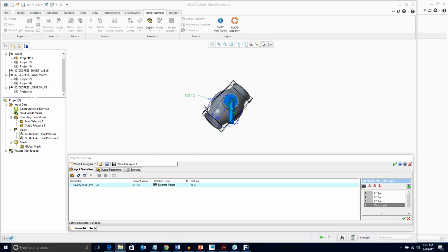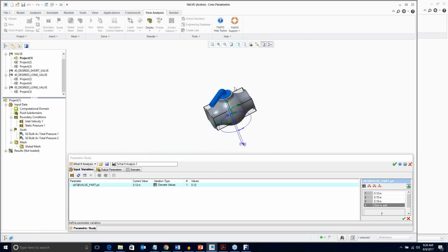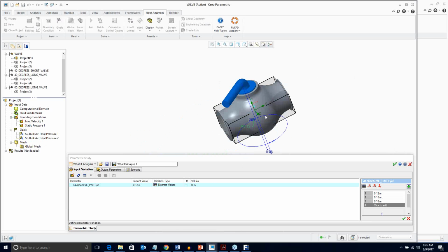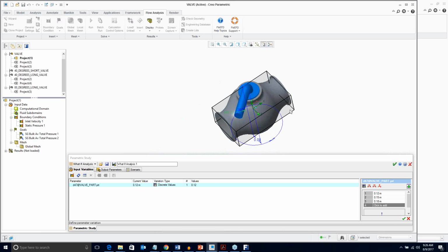That is typically applicable in a lot of CFD, especially whenever you have a case like this where there is no inlet or outlet region whatsoever. It is one of the easiest checks to do: just add some length after your flow region, and then rerun the analysis again.